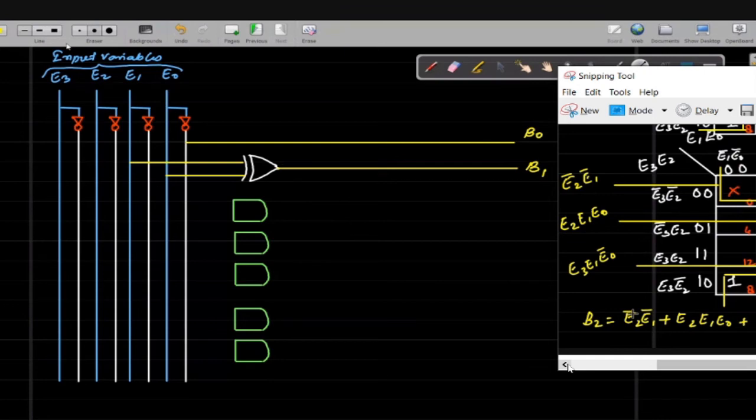And you also require two OR gates, because you are going to use two-level AND-OR logic to implement this SOP expression which you get. So let's draw a three input OR gate like this. Similarly, a two input OR gate for D3.